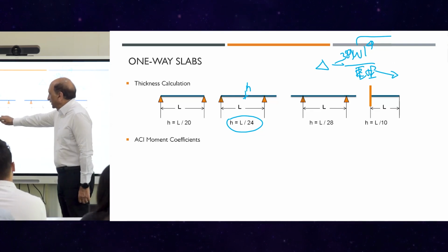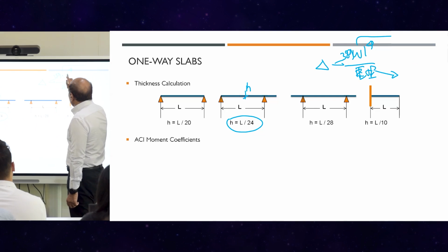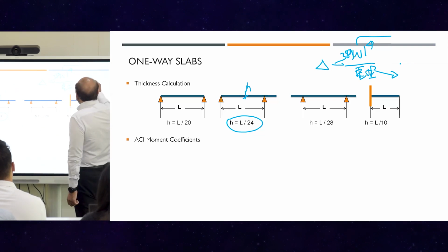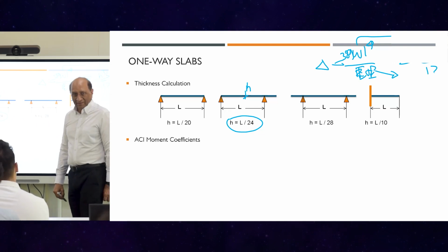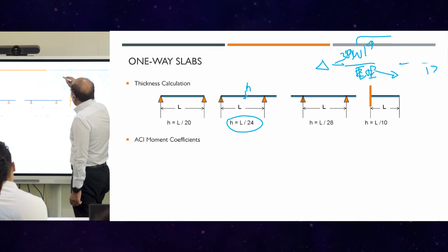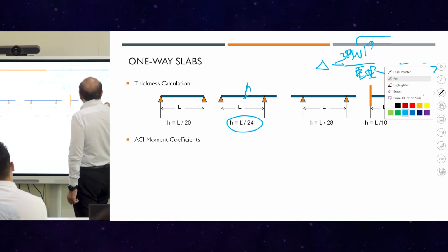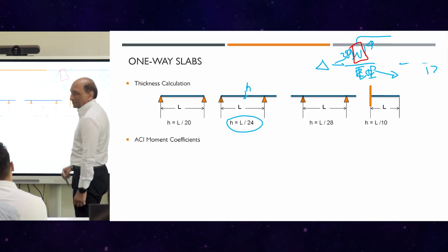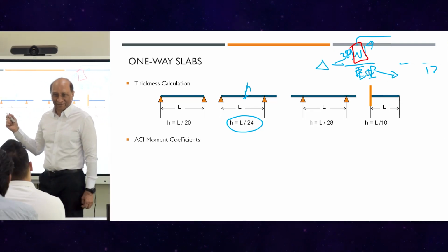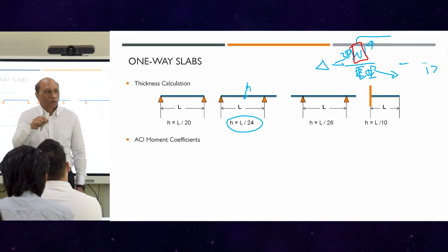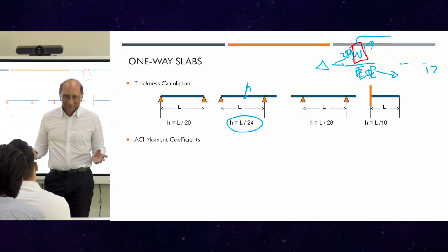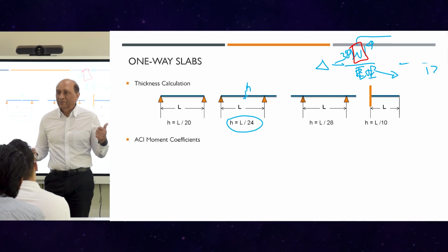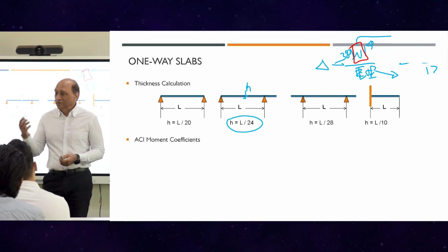But this is based on length, which is already in the formula here, and it is based on H, which is the indirect calculation from the I, because I is equal to H cubed B by 12, like we said earlier, right? But the deflection also depends on W, which is not considered in this range. So if your load is double than his load, your deflection will be doubled straight away, right? So this formula would be wrong by 100% or 200% depending upon your load.